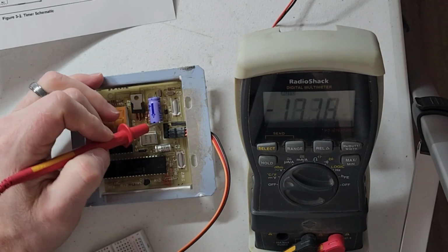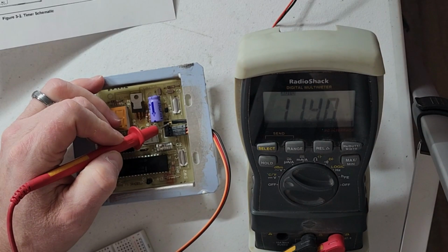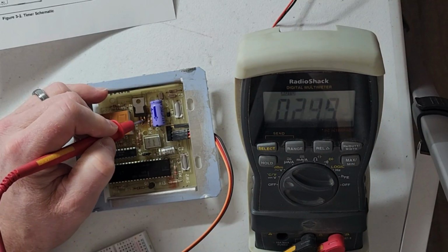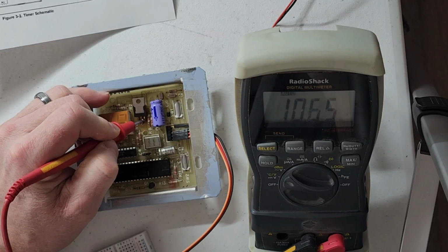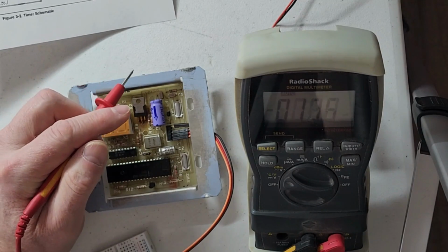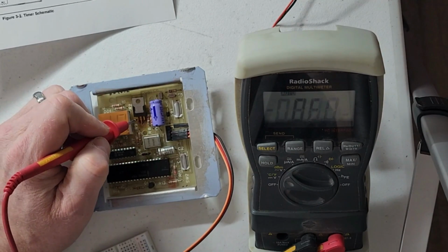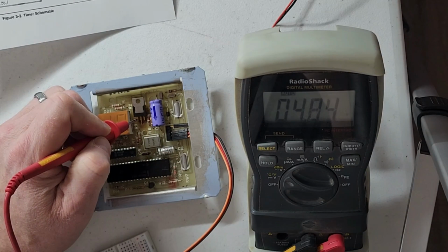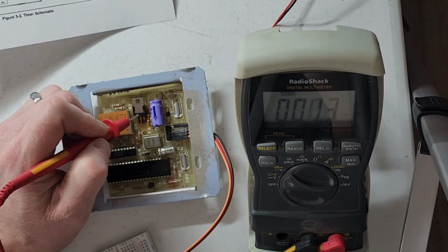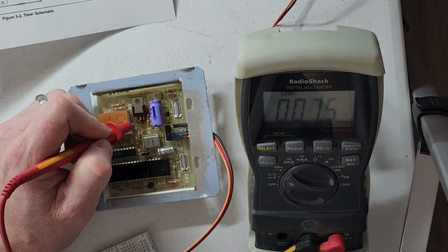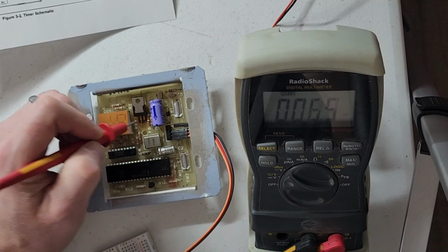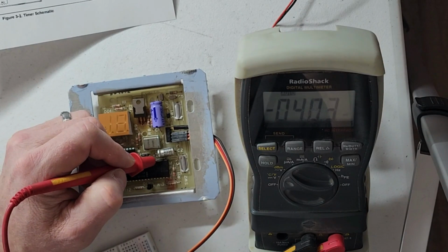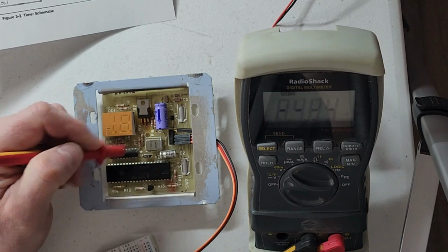First of all, let's just see. I know we got 11.4 volts coming in. Here's this voltage regulator. 10.6 because there's a diode drop there. It's regulating it to 4.84 volts, which I think is within spec for a 5-volt regulator. This should be ground here. It is. So our 5 volts is working, obviously, because we saw 5 volts here anyhow on these pins.